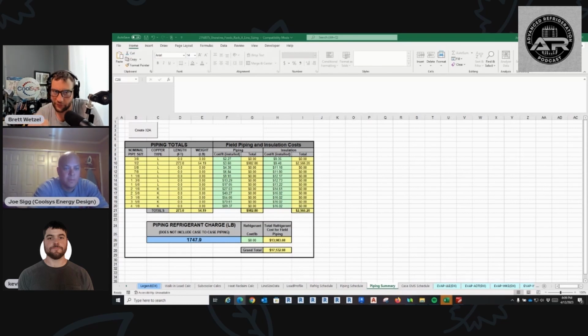So my question is, do you size for how much refrigerant you have out in the line size, and let's just say you're going to maintain a 20% flash tank level? Yep. So you assume whatever that level is, plus that's how high, so you don't get all the way up to 100% because you typically cut off at 80. Real simply, we take our refrigerant charge out in the field piping, take 25% of that, and then multiply that by 60% so that we're not filling the flash tank. And then that's what we tell the OEM, and they help us size it basically.